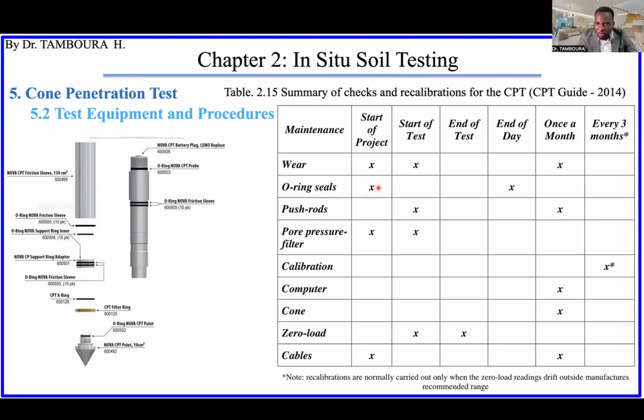At the start of the project and at the end of the day, we need to check. The pushing rods: you need to check them at the start of the test, because if the pushing rods are damaged or not straight, it will affect your test.